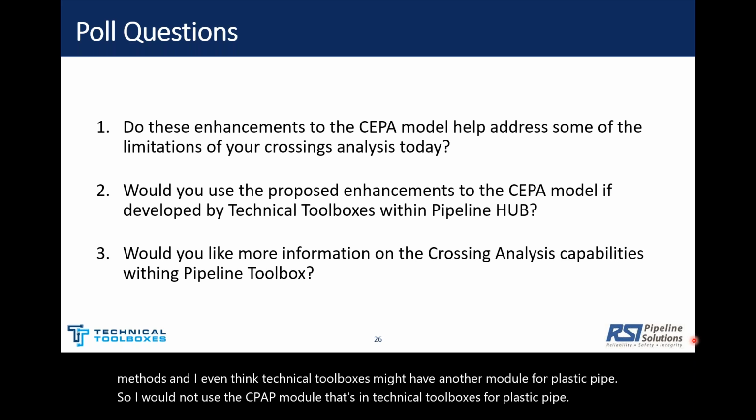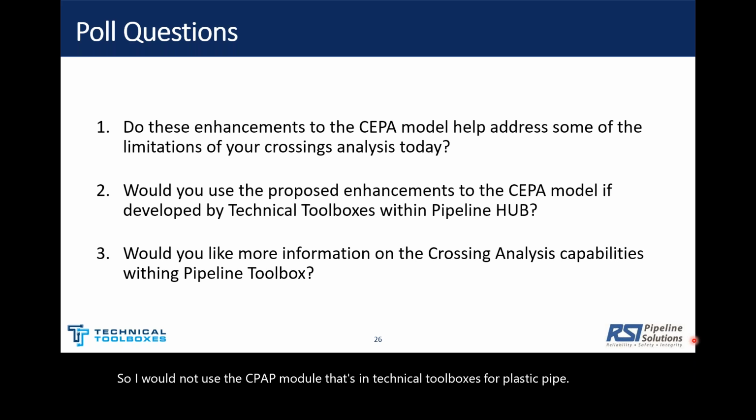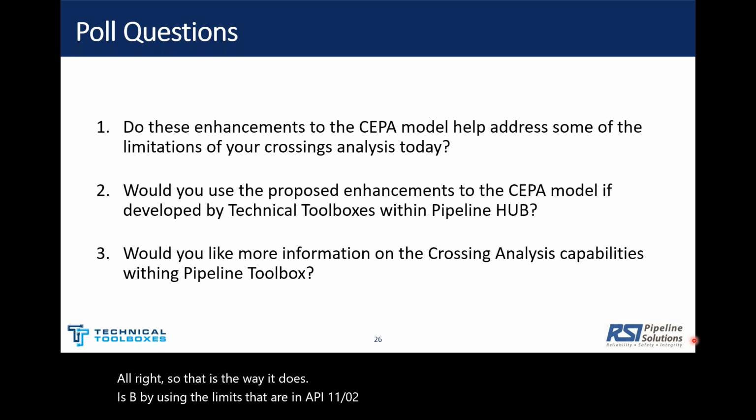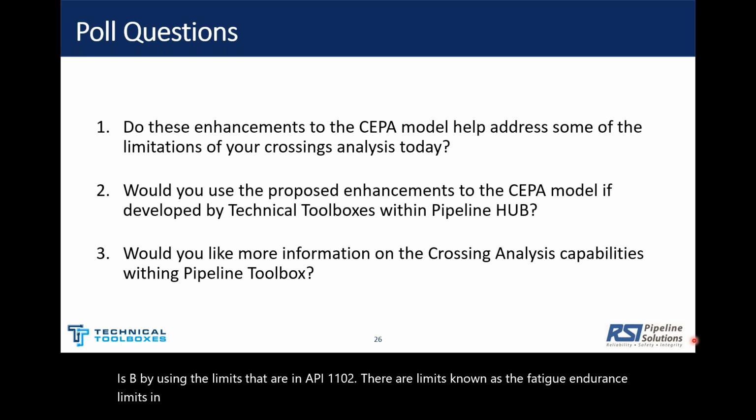Okay. How does the CEPA model factor in cyclic fatigue? The way it does this is by using the limits in API 1102. There are limits known as the fatigue endurance limits in API 1102, and CEPA simply compares the live stresses from CEPA calculations against those limits.